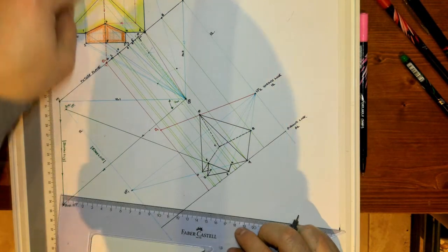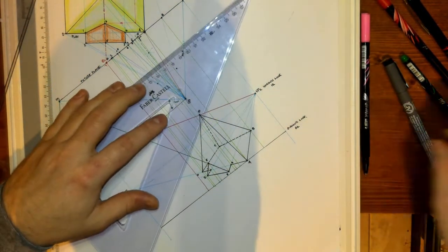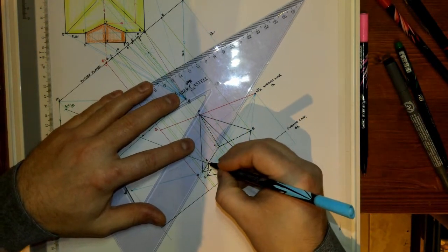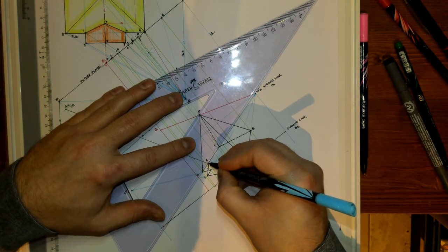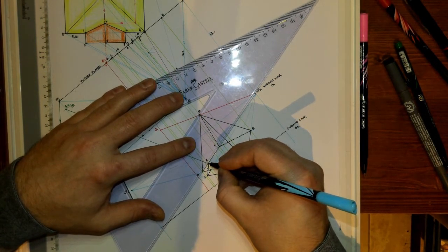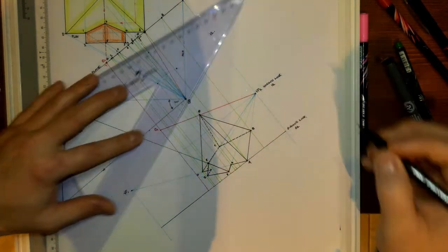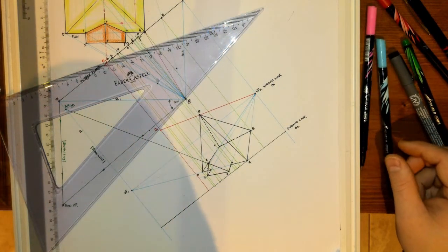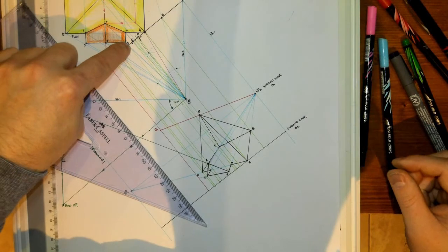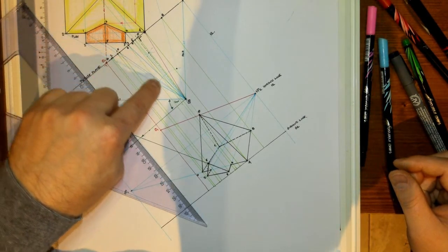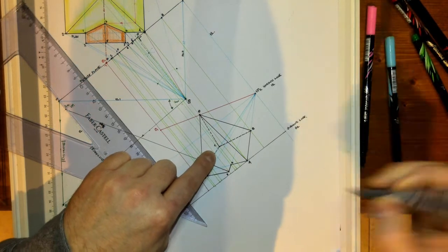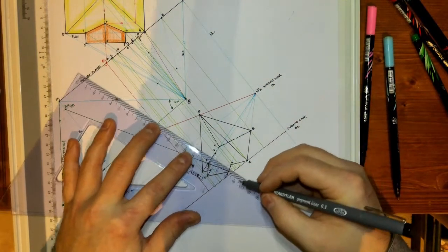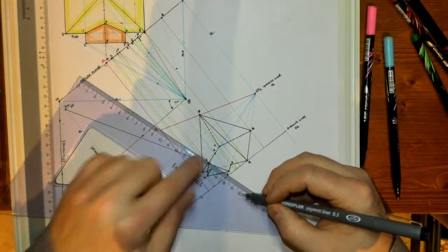And now we want to find point 6. Now, given that we have point 5, all we have to do there is join point 5 back to the vanishing point 2. So I line up like so and draw back, and I have the vanishing line going back. It kind of lines up with that hidden detail line at the back. What I do then is I track down my line for point 6 from the picture plane to intersect that line, and there it is right there. Okay, and what I can do then is I can join from point 4 to 6, 4 to 6, right here.